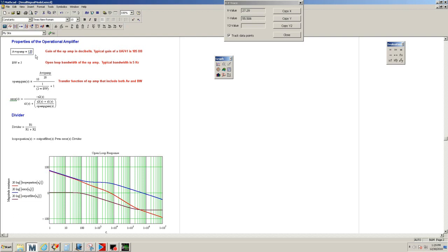So let's go. Okay, notice now it's creeping up. It's going to match close to this. Okay, so now I go another, let's say go to 160. Now if you notice, basically catching. Okay, so let's go to 200. Yeah, that's about it. So at about 150, 160 is probably where you have enough gain to compensate for that.